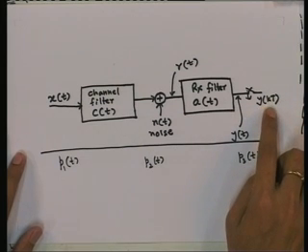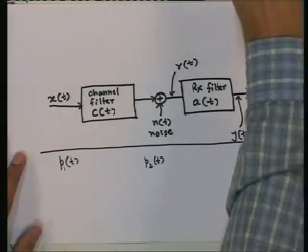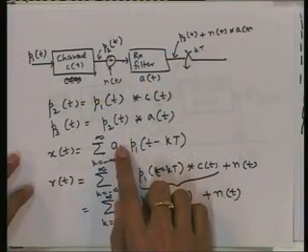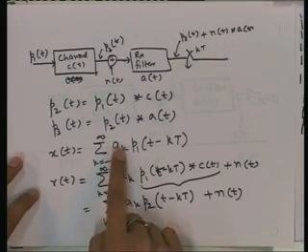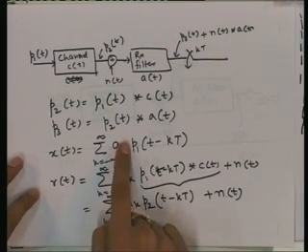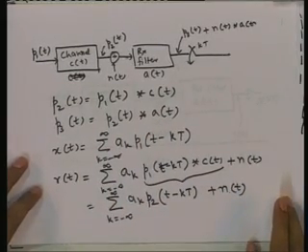At the sampling instant (k plus 1) times capital T, we will have a_k times some constant plus a noise term. From there we can estimate a_k, which tells us what was transmitted at the transmitter. If we are able to estimate a_k, then we will be able to estimate the bits that were transmitted in that symbol also.